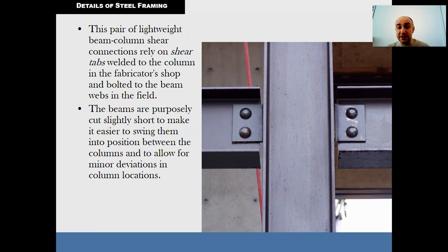And seated connection. A seated connection uses an L-shaped bracket to connect the parent and the child member together. However, similar to the angle connection, they can also be welded and bolted together. They are normally attached with a stability bracket, which is connected at the web to the flange of the additional member.